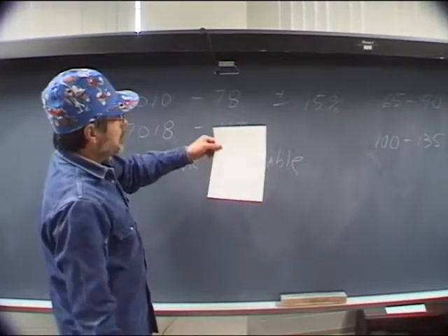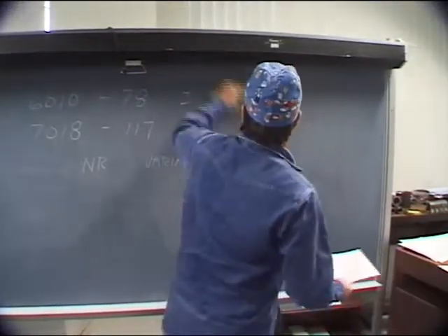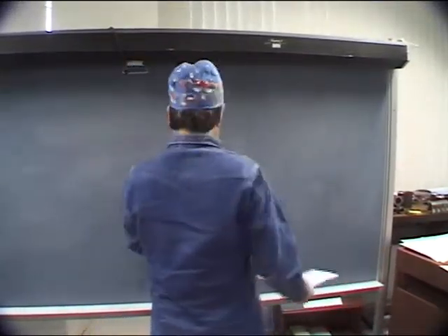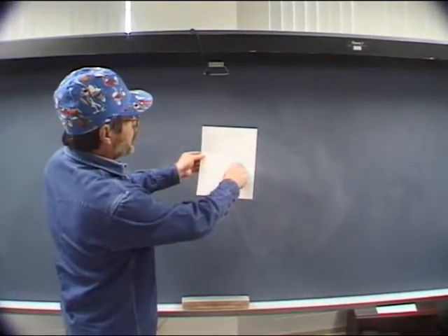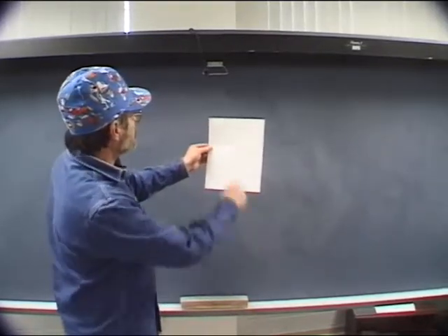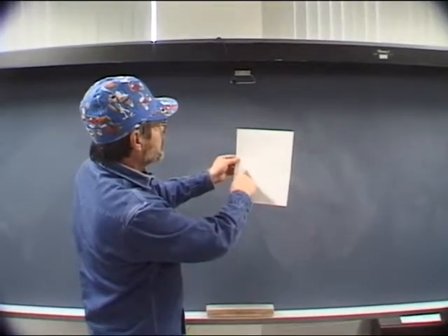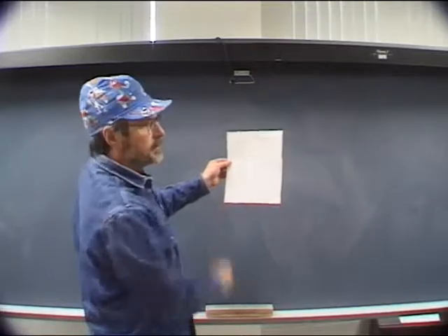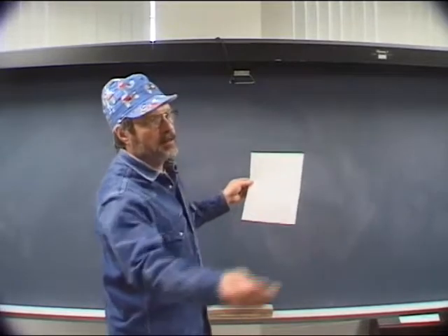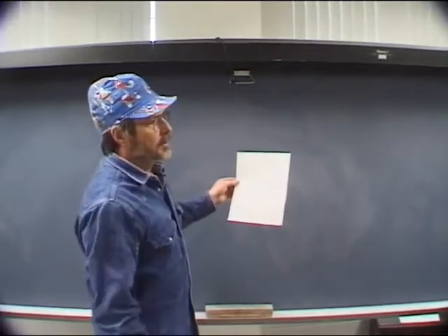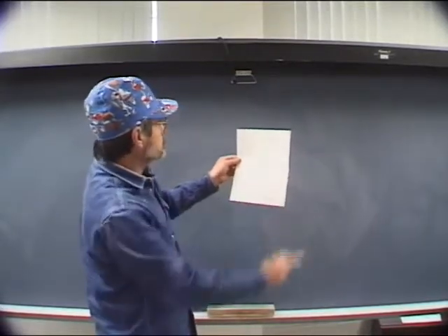Under technique, well, sometimes a person's going to be wanting to weld in the flat position using this procedure, and if they're welding in the flat position, they're not going to want to use only stringer beads. So under technique, we would write string or weave, so that we tell them they can use either one, it doesn't matter. Orifice cup size has to do with gas, that's not necessary. Initial and interpass cleaning, here you would write in the details of what you expect the welder to do. Well, he's going to grind the mill scale back away, for 1 inch from the joint, blah, blah, blah. He's going to grind and brush as needed each individual pass. All that information would go in there.